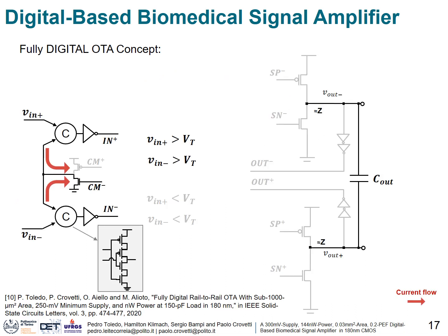Knowing that, in the last year, a very interesting idea has been proposed using a Muller-C gate in which the input common mode signal could be tracked and cancelled through a self-oscillating threshold sample loop. Using this structure, we can charge or discharge the output node of the Muller-C gate, fixing the common mode signal. If you want to know more details about this implementation, I strongly recommend the paper below.